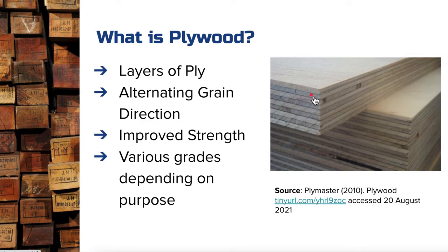Now, I'll go through the production process later, but when we're thinking about plywood, they use various grades. If you're working in the construction industry and you just need a piece of plywood to use temporarily, you're probably going to be using a really low grade board, like a D grade board. In a D grade board, you've probably got defects on both sides, and enormous holes where the knots have fallen out of the veneer and haven't even been filled back up again. So we're probably using really low quality boards.